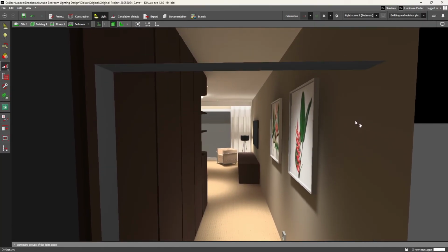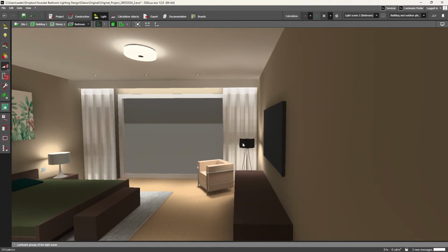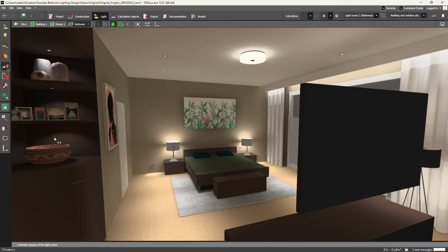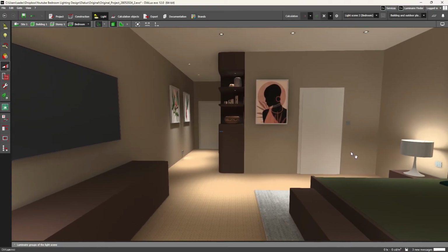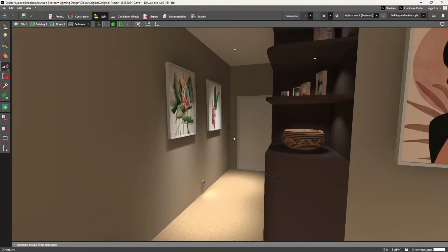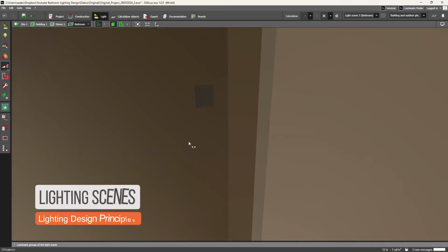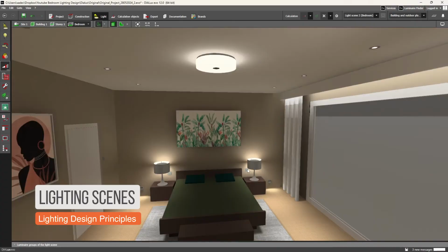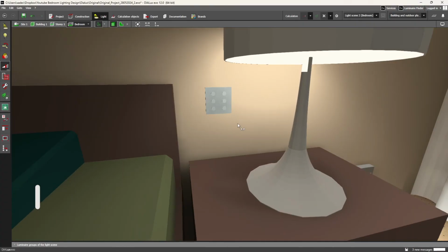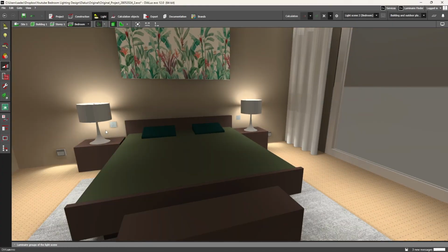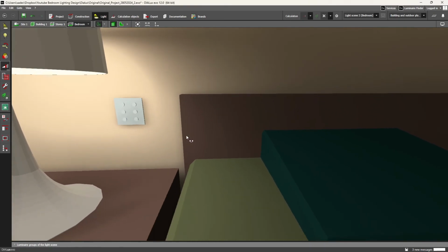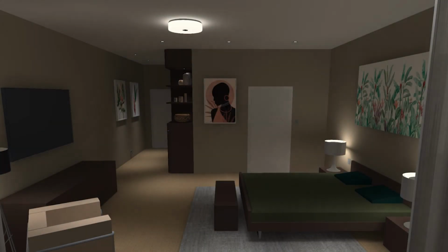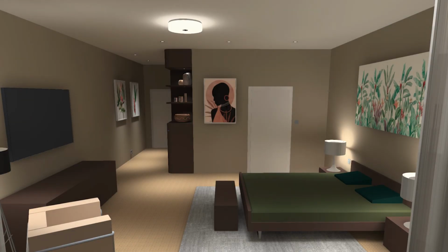Now, since all those fitting types are dimmable and are all part of separate electrical circuits, I can control them separately to create lighting scenes. Look by the entrance of the room here. I will have a lighting scene control plate, or keypads as some of us call them. And I'll have those as well on the right and left hand side of the bed. From those keypads, first, I'll be able to switch the light in a room to a bright level or full on, as we can see here.